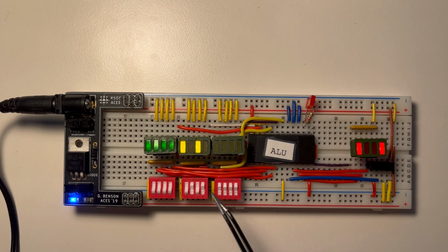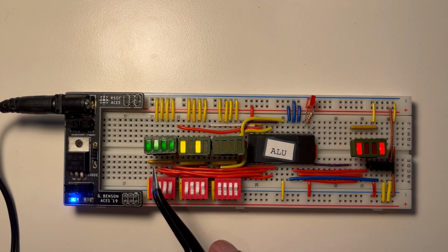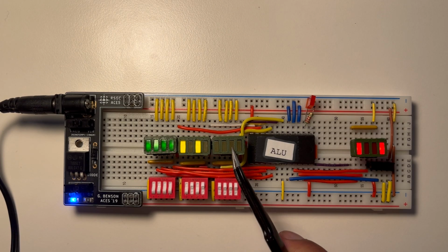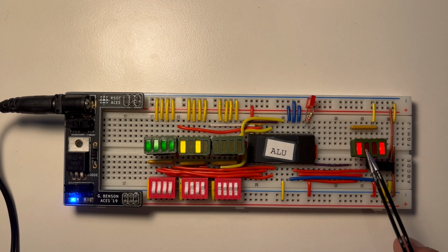Using this ALU Explorer circuit, I will demonstrate 2 arithmetic and 2 logic functions. But before I do, I'm going to describe the layout of the Explorer. So essentially the green LEDs here display the function sections, which selects which function of the ALU is used. These 2 yellow nibbles echo the inputs, and finally the red nibble is the outputs.